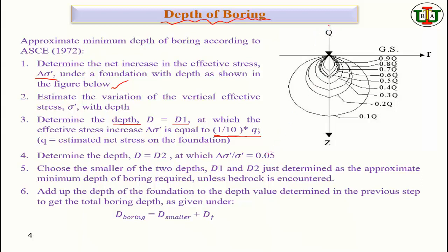If it is total Q, it is the load. If you consider small q, that is the estimated net stress on the foundation. So what is the difference between load and stress? Load equals stress into area, F is the load, right?